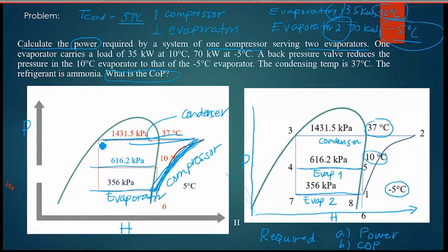What about this vertical line on the left? It's the metering device, meaning the regulating device. The general term is metering device, but the engineering terms are TEV, EV or TXV.